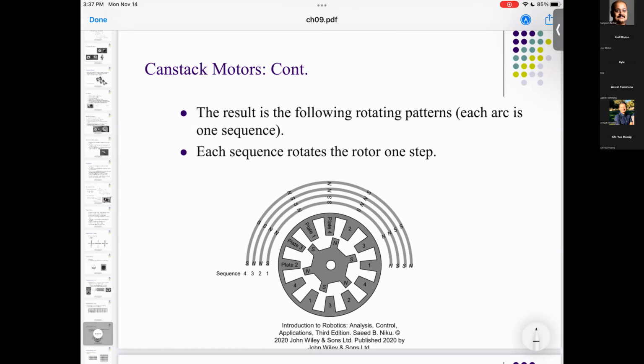If you look at the stepper motors, there is unipolar, bipolar, and again, there are different variations of the stepper motors. There are different stepper drivers, and depending upon how you pulse, there is a concept called micro stepping. So you can actually have a resolution finer than the stepping resolution. Stepper motors are a huge topic in itself, and the idea is they are a low cost alternative for robotic applications, but they don't have feedback.